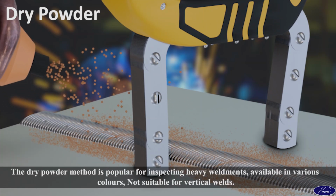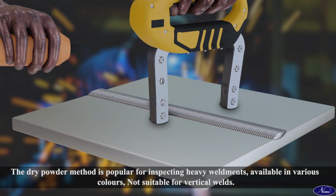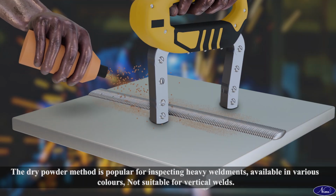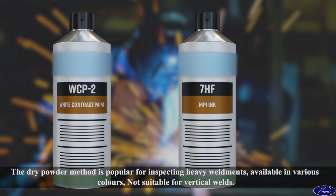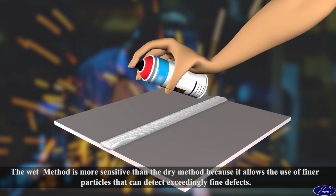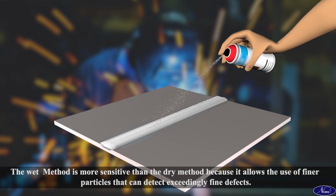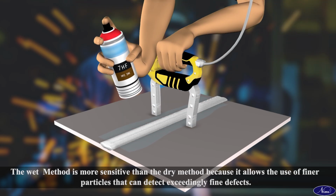The dry powder method is popular for inspecting heavy weldments, available in various colors, but not suitable for vertical welds. The wet method is more sensitive than the dry method because it allows the use of finer particles that can detect exceedingly fine defects.